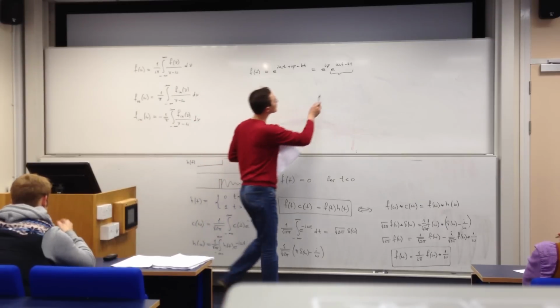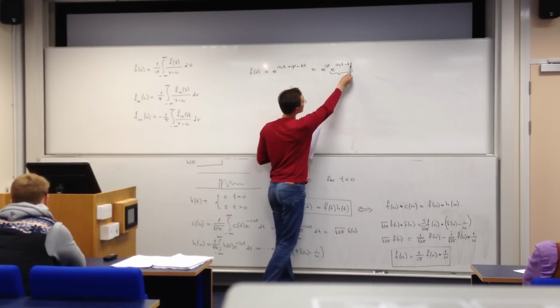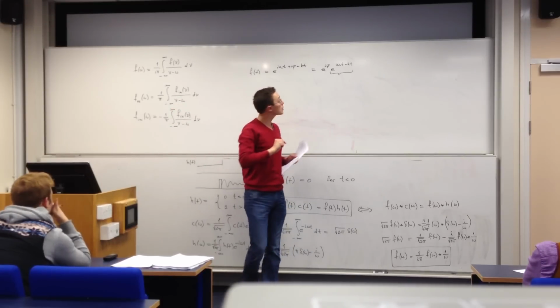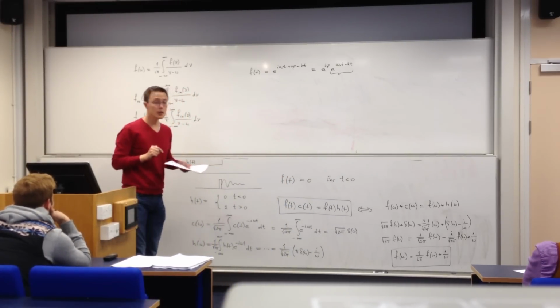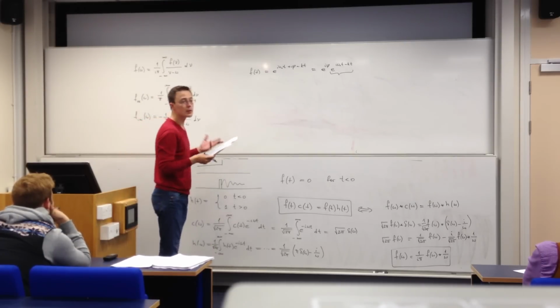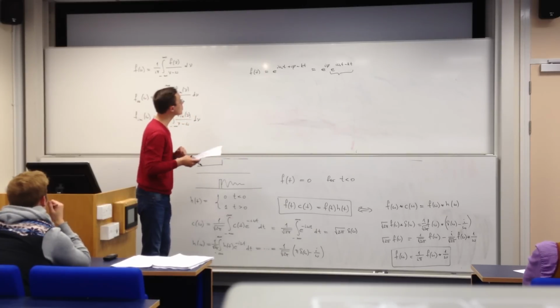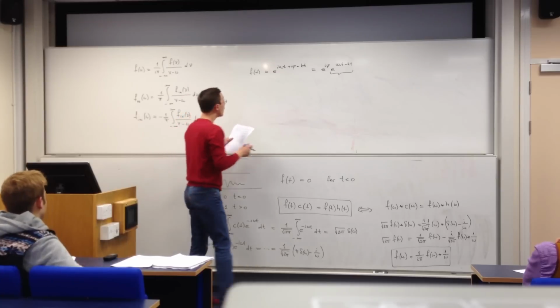So it is an exponential with an oscillatory component and a decay component, which is real, as you can see, and so it's just a decaying oscillator. Let's do a Fourier transform. It's a trivial exercise, but it is highly instructive to just convince yourselves that the shapes of your signals, when they come out of the instrument, would have a Lorentzian shape. Right.